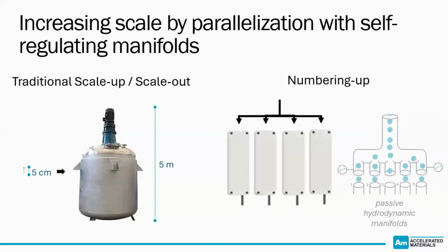And let's compare the annular flow and the traditional batch systems. In the case of the flow reactors, you need to have a good manifold that can split the flow equally, and you can achieve the scale up by just numbering up of the reactors, right? In this case, you need to optimize the reaction conditions or process once for one reactor, and after that, the scale up becomes quite an easy task. It's much more difficult for the traditional setup.